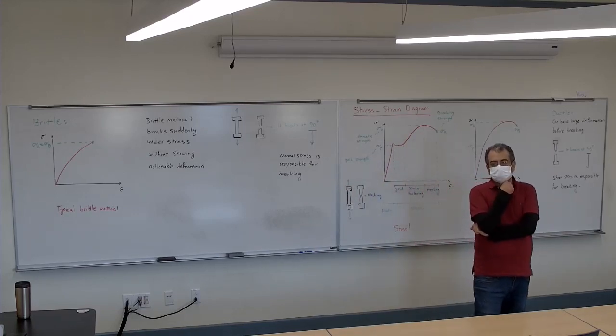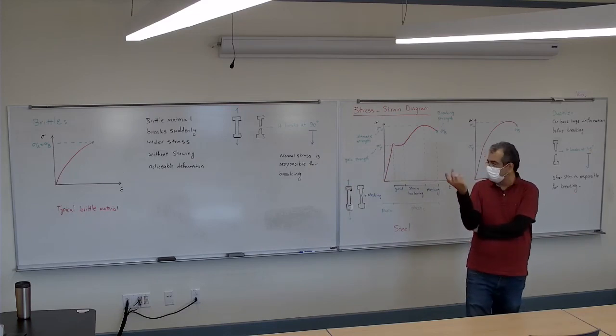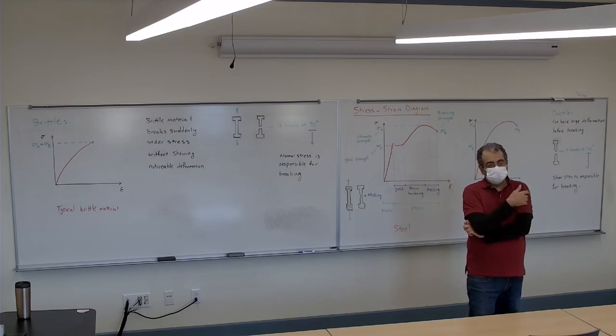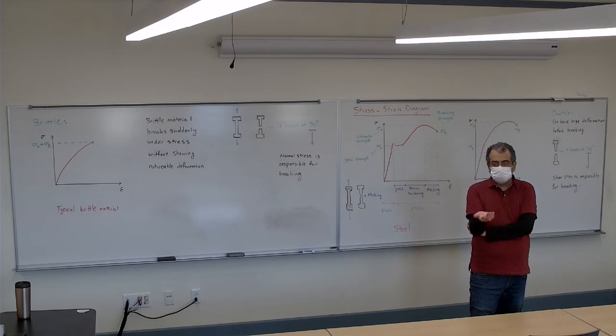Concrete does a lot better, I'm pretty sure, under compression than it does under tension. Concrete doesn't do much under tension. Usually in the design you completely ignore it, you say okay, it's just useless under tension. But it does really, really good under compression.